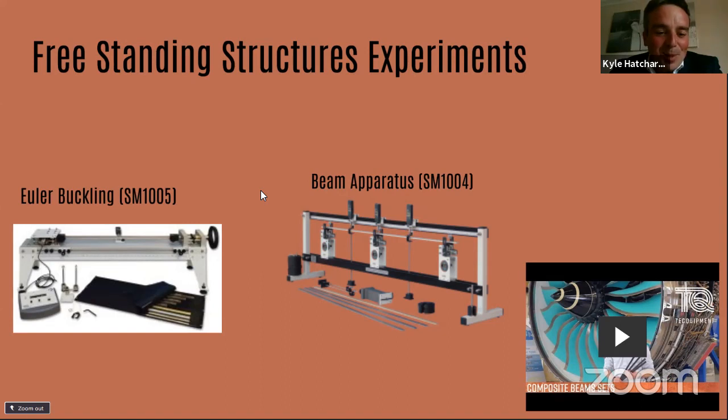So when we spoke about the Euler buckling of struts, effectively you've got various different fixing points on that piece of equipment. So we have a structures range that effectively covers the same principles. However, this is a benchtop version and allows you to understand the failure points, really, the point of buckling. And that's important in applications such as a steering rod that goes into your steering wheel in a car. You need to know the point at which that's going to fail, because if you have a front impact of the car, you don't want that to pierce the driver. You'd like to make sure that that particular piece of material is going to fail, and you would use Euler buckling to calculate that failure point.